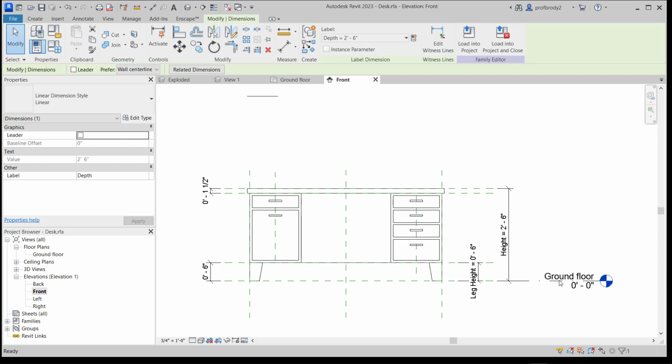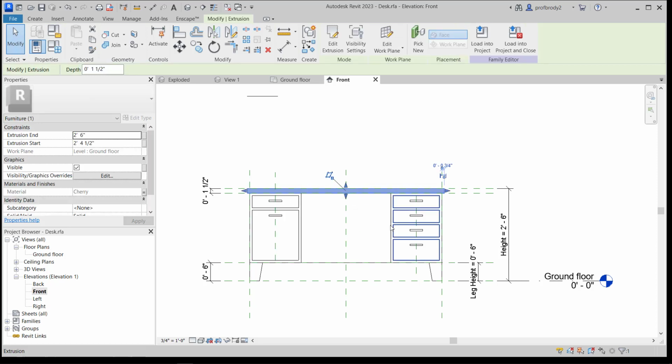You can see here there's a reference plane, that's the ground floor, and this object is placed on the ground, so that is your main reference plane that's kind of external to the object. And you may have noticed that when you import components, often they only want to go on walls or floors or ceilings. But the other thing is you can reference vertical elements as well and lock these objects to those vertical planes. See here, this is the work plane reference lock, and this object is locked to that vertical height. Again, when you go into your main project, you can change that height.